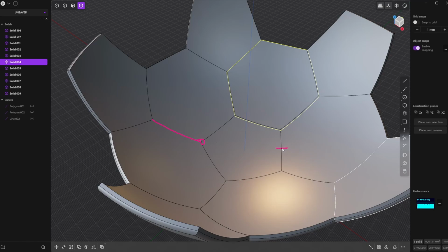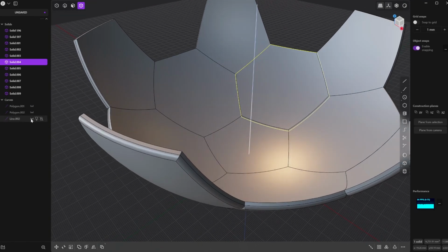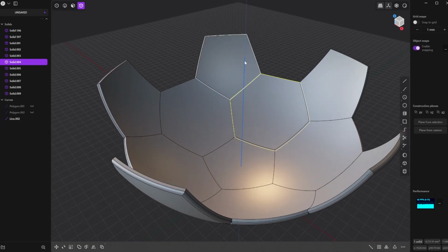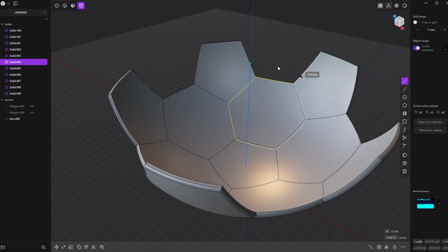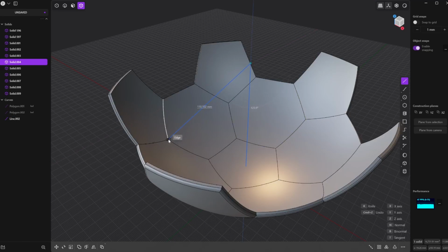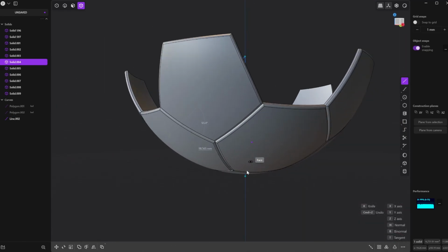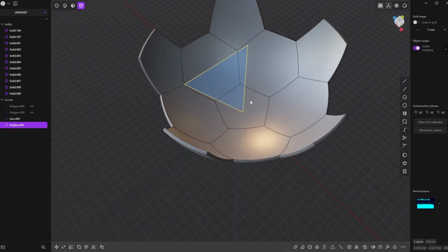So if we rotate this hexagon around the center of the sphere, that edge is going to be here. Let's do that, bringing back the initial construction line that represents the center of the sphere, using polylines to build the construction plane.